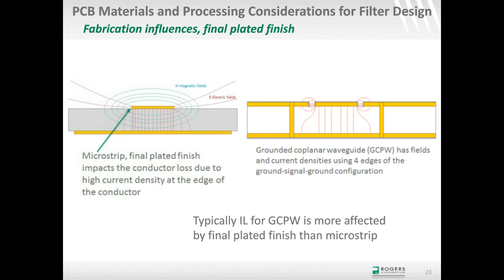So a short length circuit is not going to be impacted too much by this final plated finish for insertion loss. However, if it's a longer circuit, these edge effects kind of add up. They accumulate over the length of the circuit, and then there is going to be more insertion loss due to this edge effect for the microstrip.